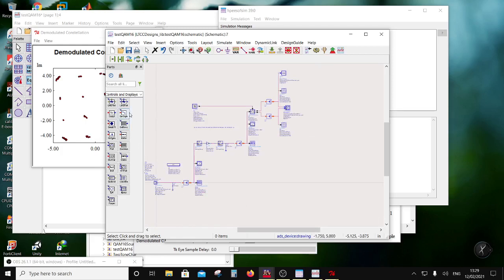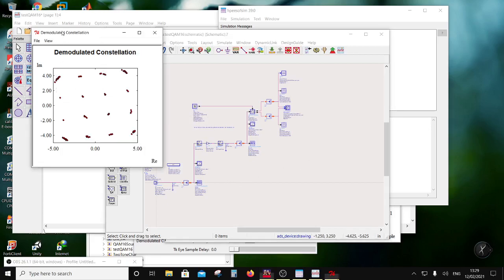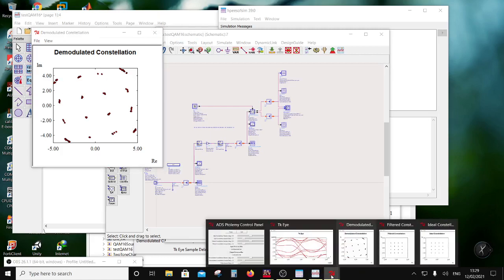So for EVM with the reference, okay, one more thing is there. I want this to be -1 -1. Because there is an amplifier, right? So now the gain is 17.6. So I bring it 3 dB down on the two channels. So that's going to be -3. And then I have to do a square root for voltage. Then that would be again 3. So I have to subtract 6 from 17.6. So 11.6. So I have to put a pad of 11.6 to get this in 1 1. Okay. So let me just stop this.